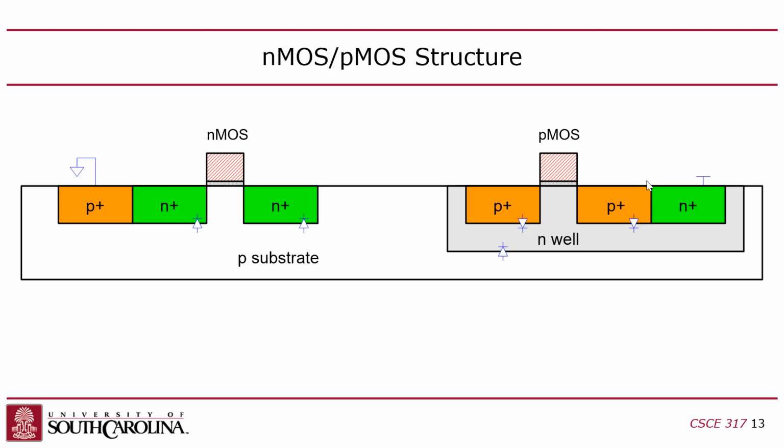And then there's contact layers. Every layer, well, not every layer, the active layers aren't, but most of the layers are separated by silicon dioxide glass, right? But if you want to connect two layers vertically, then you put a via, which is like a little hole, and that allows you to flow metal down. Or in this case, you actually have metal that flows down onto that contact there, onto that diffusion. So that's a layer, called a contact layer, which is this.